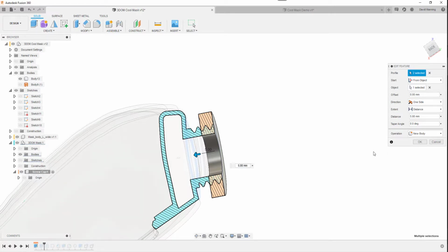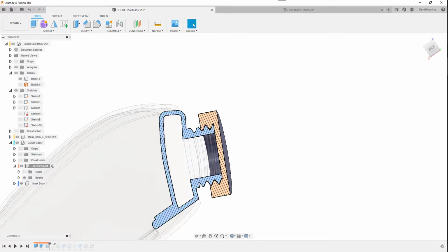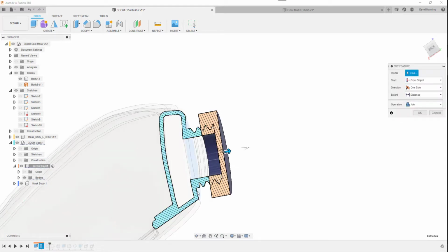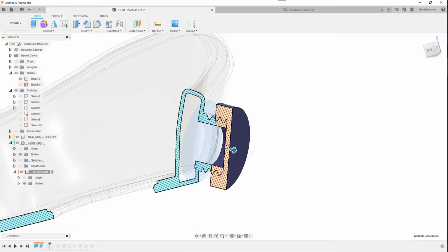The next thing I did, let's cancel that and go next, was to project the same body. So we selected the profile planes, which are the 3 rings from the outside and the inside and the hole, and I projected from the surface of the first part I created, and I projected it further up by 2mm, being the thickness I wanted, and joined it, which gives me the body that I need. Let's trot that back.